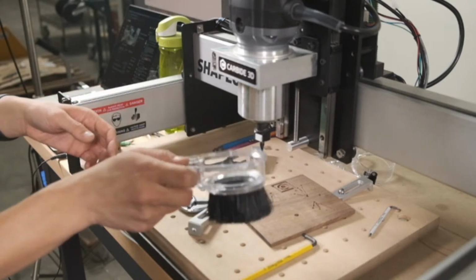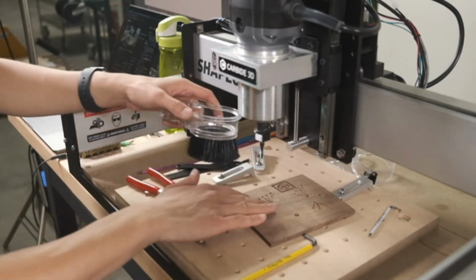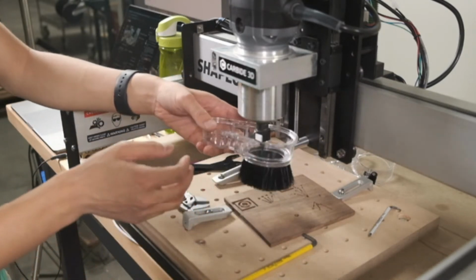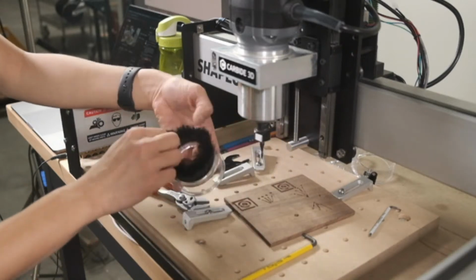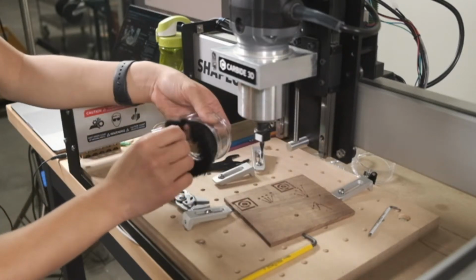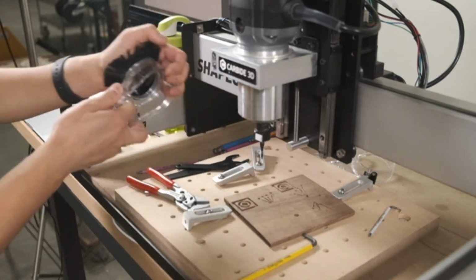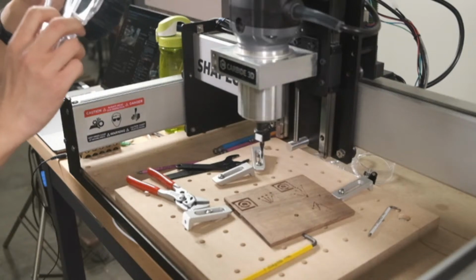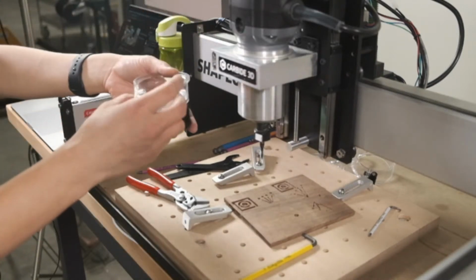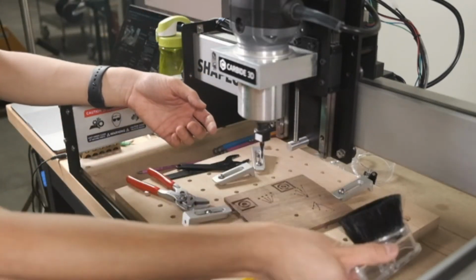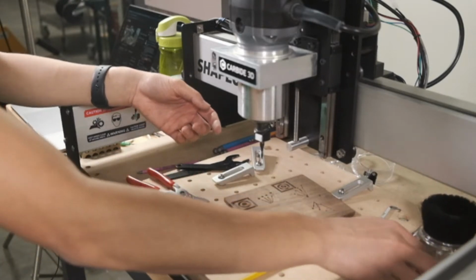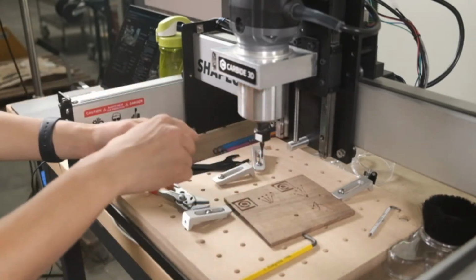So that's why you should try and just set your bristles so they're just lightly touching the surface at your desired depth of cut. We are getting some really soft bristles on the Sweepy that should work really well without causing these issues. But yeah, there's just dust collection, dust boots. That's one thing you have to make sure that you're also doing carefully and applying it in a way that's not interfering with your cut.